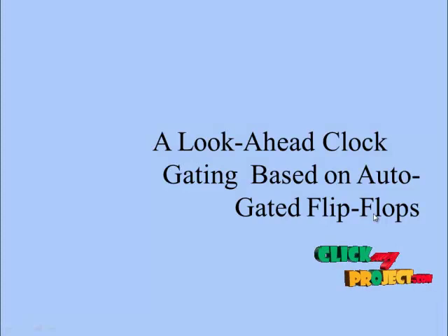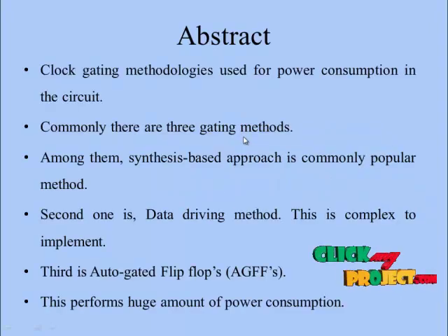Let's discuss the product. Our product is a look-ahead clock gating based on auto-gated flip-flops. The clock gating methodology is used to reduce power consumption in the overall circuit. It is not only used in flip-flop circuits. Clock gating is a general concept, and we can adopt it with any logic circuit.